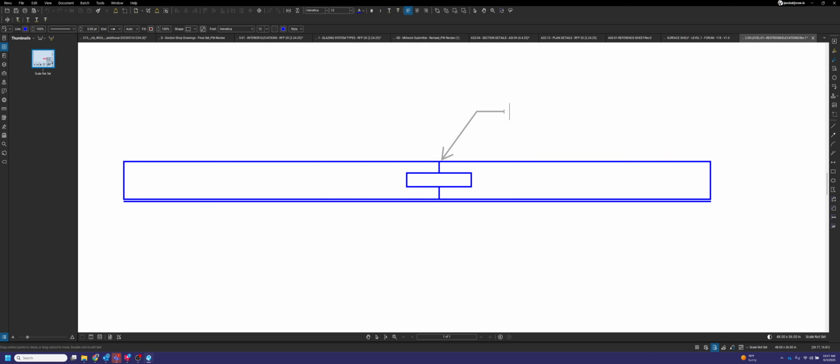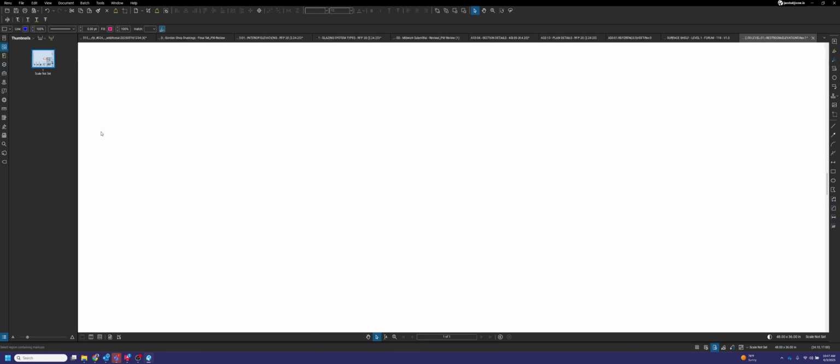If you call that out on your print, we'll call it out as an SJ. You're probably used to seeing FJ for field joint, but a shop joint is specifically for the shop to realize that this is something that has to be assembled and glued in the shop. So that's what an SJ would be. It's not a very common occurrence, but when you're dealing with larger panels like this, there may be an opportunity to use a shop joint there. So I'm going to leave that be.